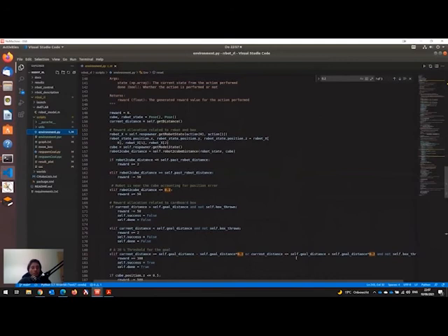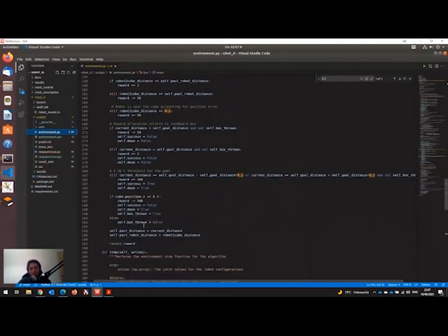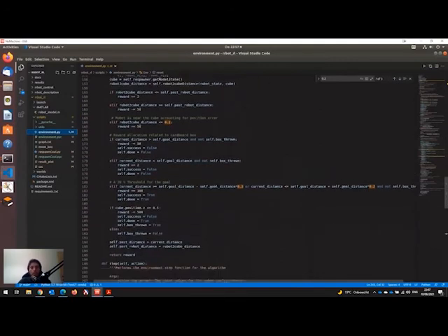The reward system is also defined here. Basically, when the robot is approaching the box, it will get +2. When the robot is moving far from the box, it will get -50. When the robot is within the range of contact of the cube, it will get +100. And when the cube is moved to approach the goal, it will get +50.